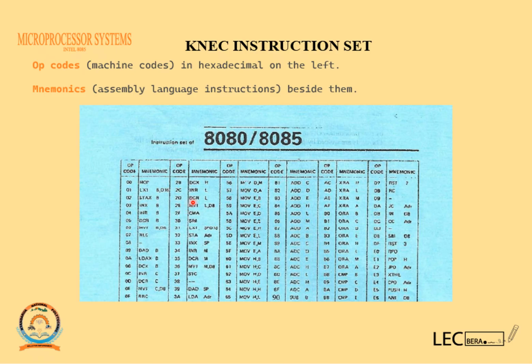If you are given an instruction and told to come up with the opcode, you go to where that instruction is located. For example, if you are given MOV E, C, that is an example of an instruction whereby we are moving data from C to register E. So this instruction, the equivalent opcode version, is this number.